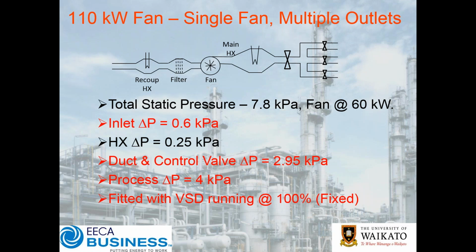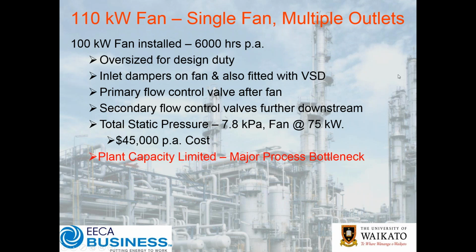And so it was quite a wasteful system, but the philosophy was, well look, we need to control and get an even flow across each of these outlets. Now of course what was interesting is because we had a relatively high process load in terms of the static pressure, there was more than enough static pressure to ensure that the flow was evenly distributed without those secondary control valves. So those secondary control valves could be completely removed. Clearly the fan was oversized for its duty.